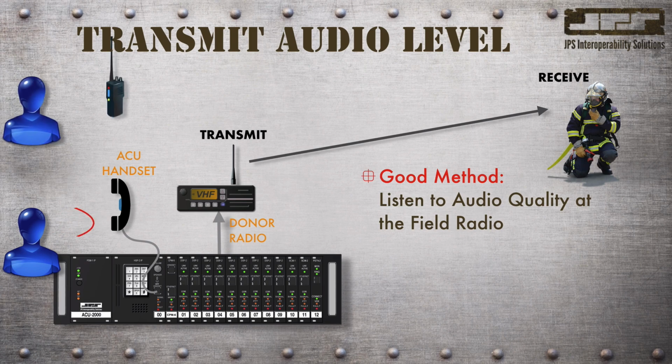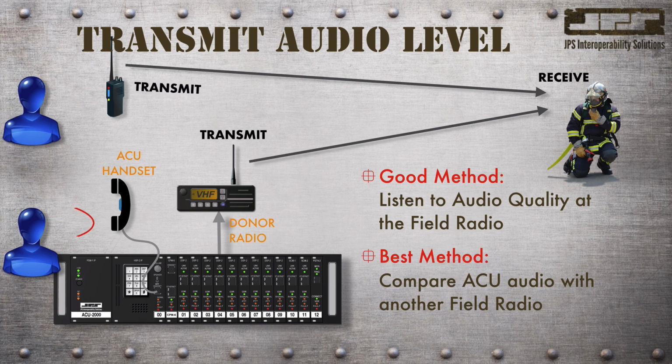A better method is to compare the test count transmitted from the ACU gateway to a test count transmitted from a supplemental subscriber unit. With this method, the volume controls of the radio in the field have no bearing on the audible differences between the transmitting donor radio supporting the ACU gateway and the standalone subscriber unit. There are many situations where an additional subscriber unit is not available, and in those cases, you can do without. Even if using the good method, you can yield satisfactory results.